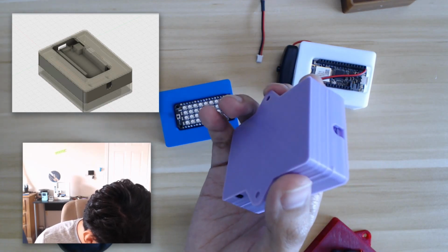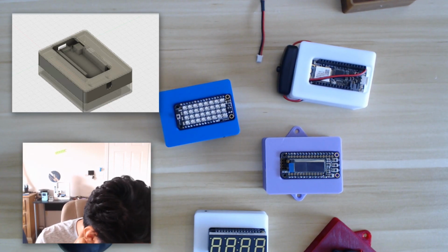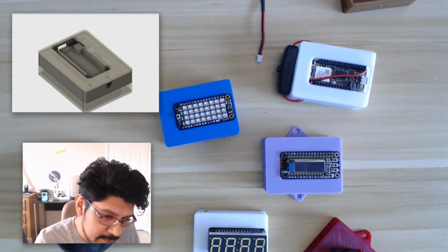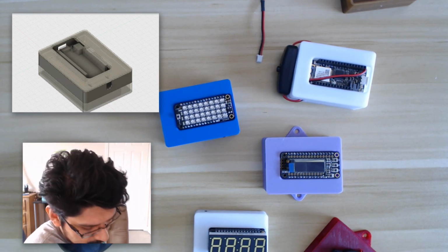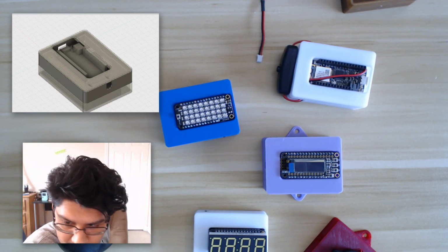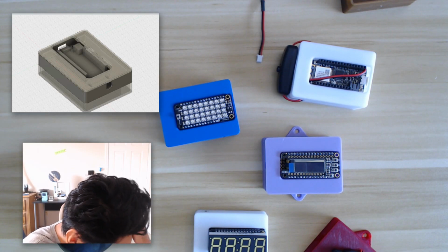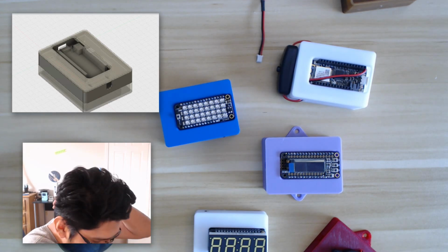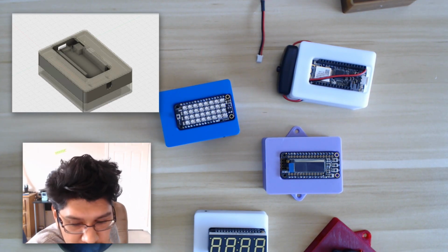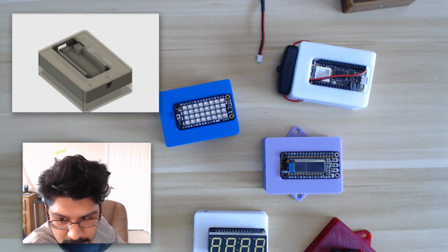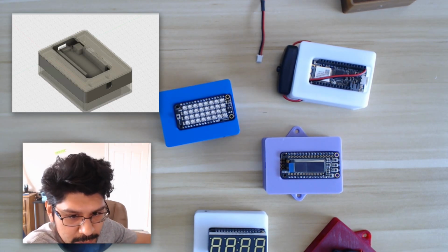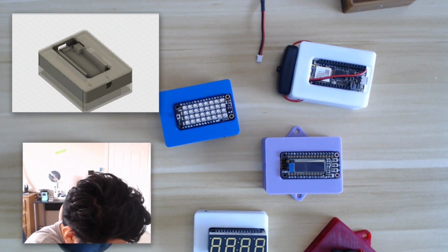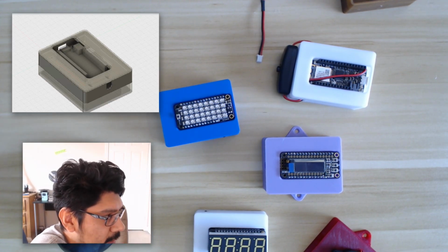I talked a little bit about reworking the master assembly. That's just the browser, all the layers inside the browser and the sidebar. I need to make it a little bit better for people to come in and quickly understand where things are. I need to take a close look at versioning. I know Fusion has versioning capabilities, but how that makes sense with this project is something I have to look into. I talked a little bit about reworking the timeline, optimizing features to reduce them, grouping features in the timeline so that they make sense, organizing features without breaking the order of operations, so making the pieces of the enclosure a generic, central version, and then making copies from those master versions so that it's easy to make another copy and to get into the timeline and understand where things are, right?